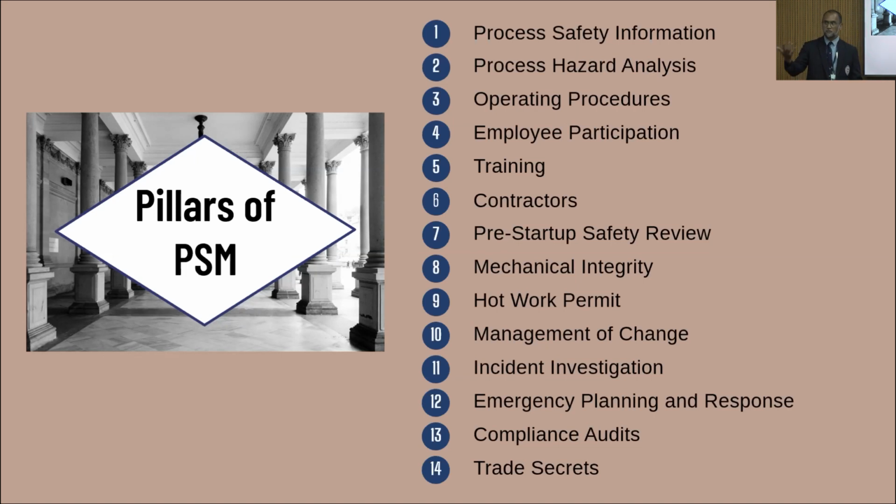When you design equipment, we talked about design just now, and we're talking about releases in the previous speaker, but you must make sure your equipment has mechanical integrity. In basic terms, that means whatever is supposed to be inside your piping stays inside your piping, and whatever is supposed to be outside your piping stays outside your piping. If you're familiar with vacuum systems, you can get air ingress into something flammable, and then you end up with a flammable mixture that you don't want. On the other hand, you don't want to get your toxic chemicals out into the open, where they can affect your plant operators and the surroundings and all that.